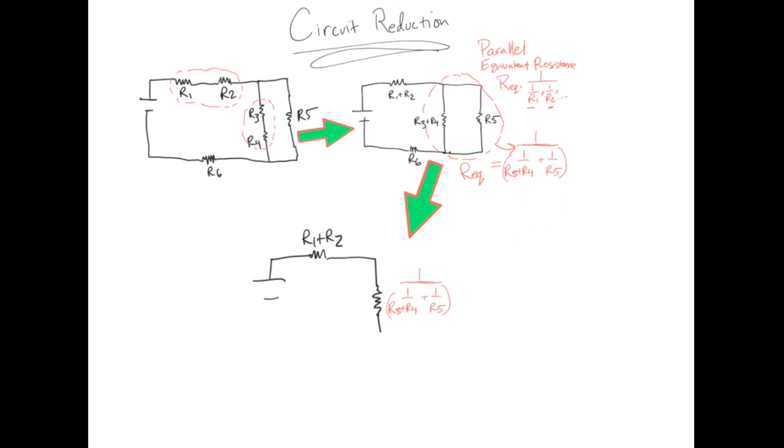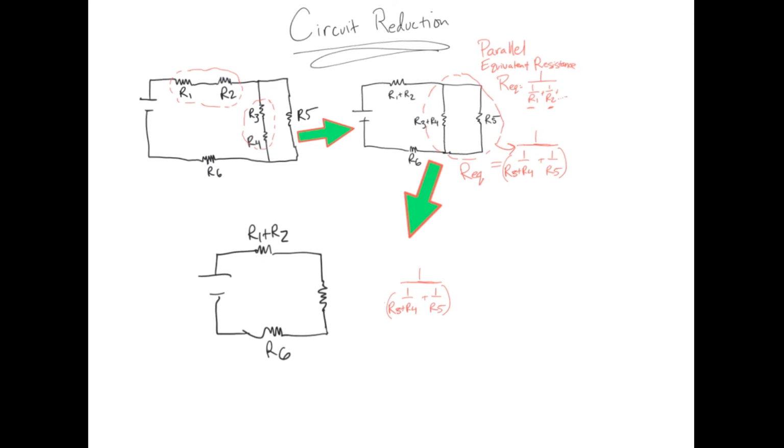The total of that resistor would equal this math expression. When you have real numbers, you can shorten these up and get like 6 ohms or 5 ohms, so it's not as much notation to keep track of. But when we're doing strictly these variables, we have to leave all that in there. So that's how much that resistor would be. And then in our part of the circuit, we're just going back to R6. So it's not like we've gotten rid of these chunks. If you go back, we've accounted for all that parallelness by representing it as one resistor of this amount. We've taken care of this series part by representing it as one resistor, R1 plus R2. Well, now you see the last step of this, that this circuit here, let me just move this whole section over.